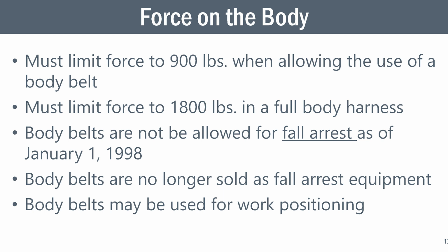Well, you take a 300-pound person with a 6-foot lanyard and they fall that distance, that's 1,800 pounds of force on the body. So automatically you can't use a 6-foot lanyard, and that's what most people do.